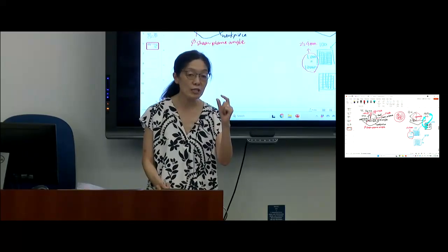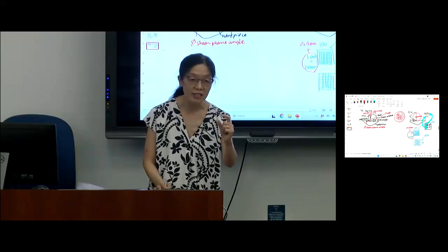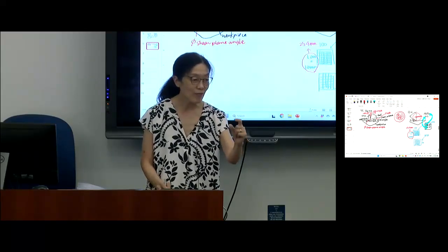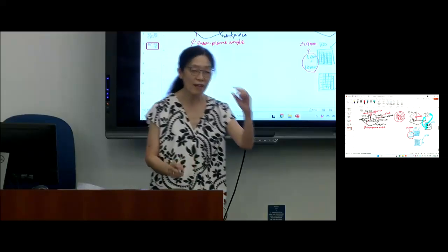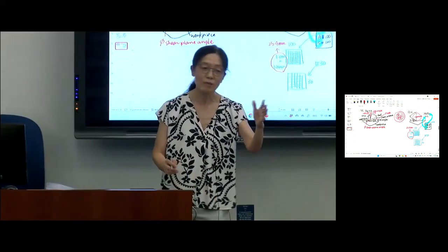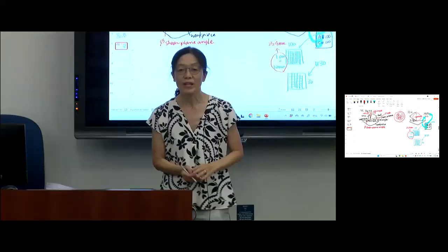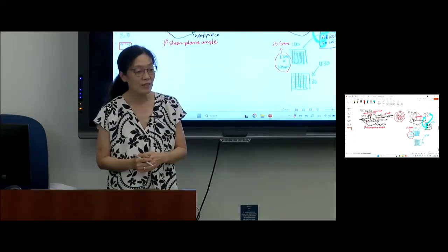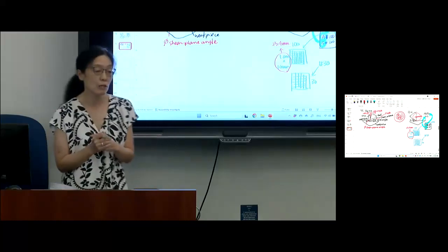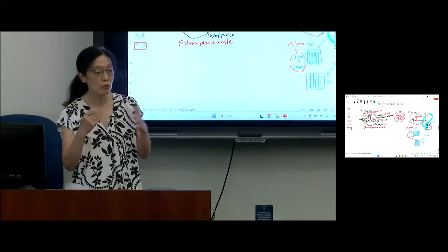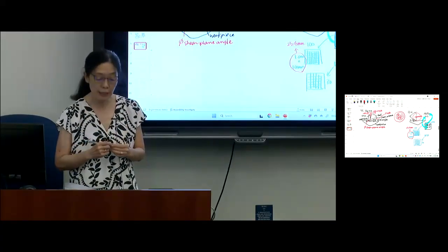When you have to change the tool, you have to stop the machine. That's another waste. And once you stop the machine and change the tool, you have to recalibrate to zero or something like that, right? Think about how many minutes you waste. You cannot do that. That's why tool wear is important, and I think Dr. Schuler gave some sort of lecture about the tool material.